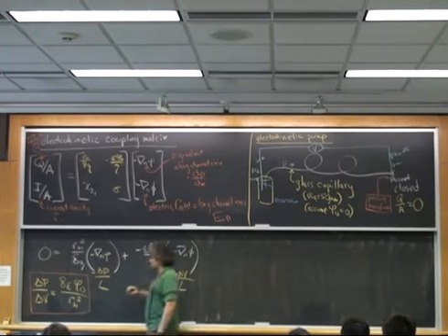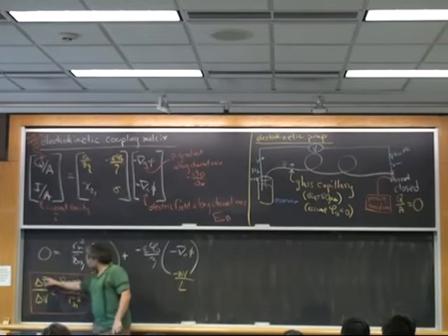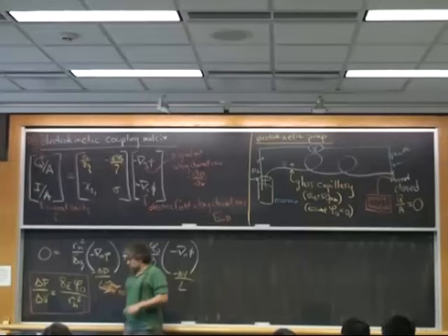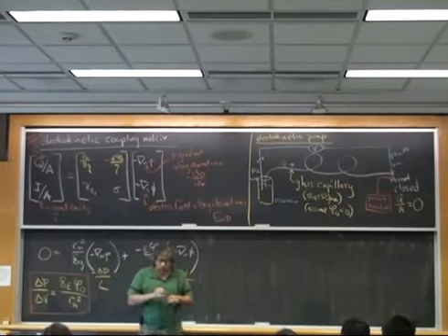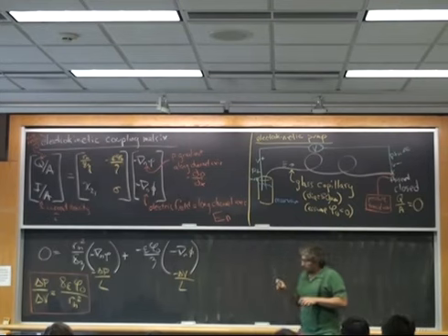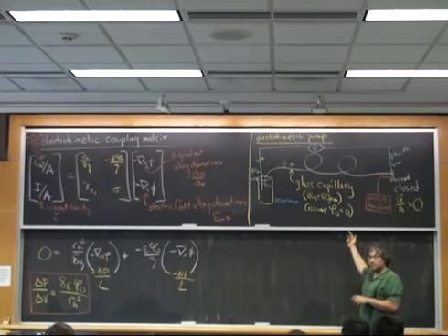But the relative magnitude of the surface-driven flow as communicated by this voltage and the pressure-driven flow as communicated by this pressure drop, these are not in balance. So I take my device, I make it smaller and smaller and smaller, and pretty soon I find I can get a high-voltage power supply powered by a battery, and I connect it up to a glass tube that's connected to salty water, and I can generate 100,000 psi.